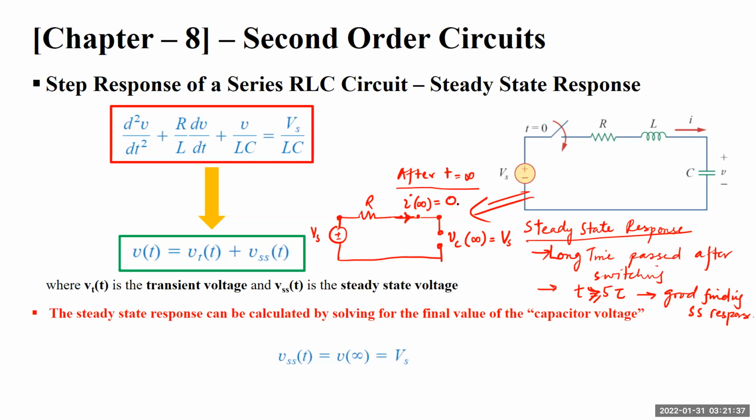Generally in this case we are not concerned with I equals 0, because we are concerned with the voltage across the capacitor. Once we develop the voltage relationship for a capacitor, we can simply use V of t for all. Remember, if we differentiate this, we get the current through the capacitor. So to find the current, we simply differentiate the voltage response multiplied by the capacitance value, and we get the current flowing through the circuit. Right, so this is how we find the response.